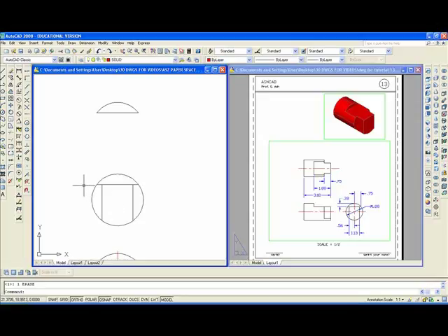Well, there's a lot of ways of doing it. I can trim. Let's say I break first of all. I'm going to break this arc. I'll pick any 2 points. And then I'm going to trim from that line and that line. Enter that and that. And I'm going to trim from this line into this. And I'll erase this.